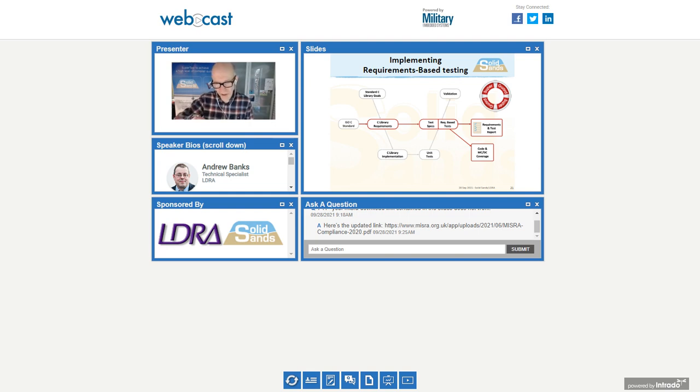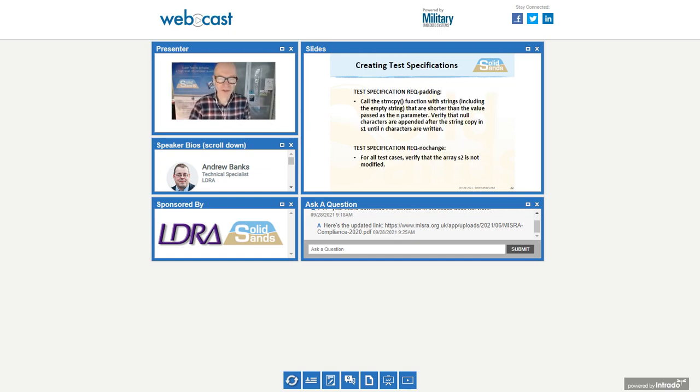Out of that, running the test, we get two reports. One is basically a traceability report with a link between all the requirements and the tests. And the second is we get an overview of our code coverage and our MCDC. I hope I pronounce it right now, Andrew. MCDC coverage comes out of that as well. And those reports are then integrated with your qualification report, of course.